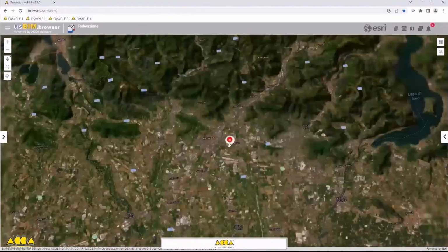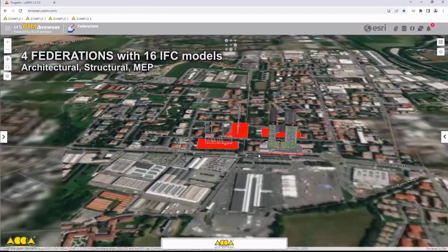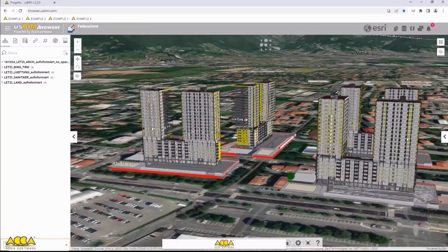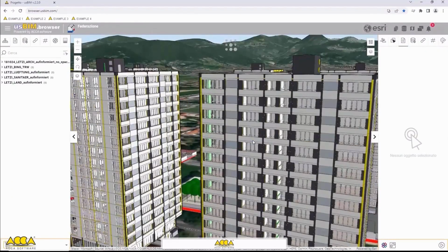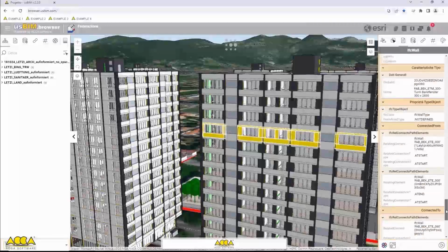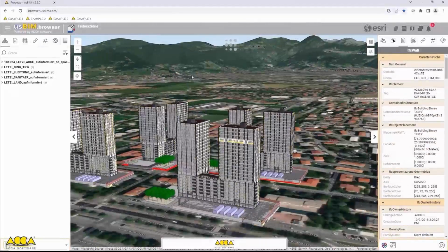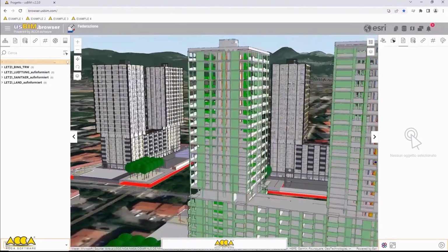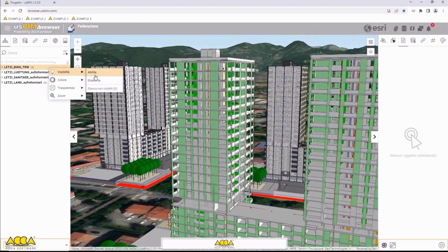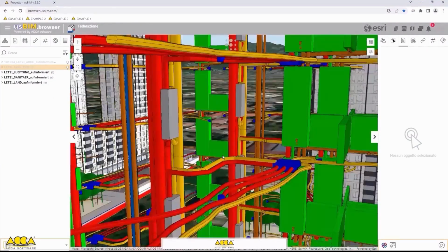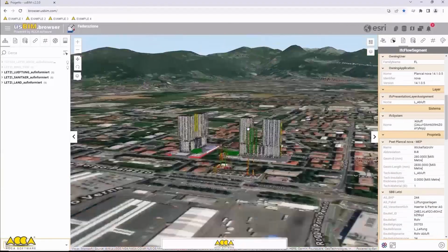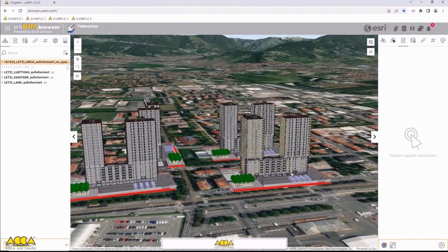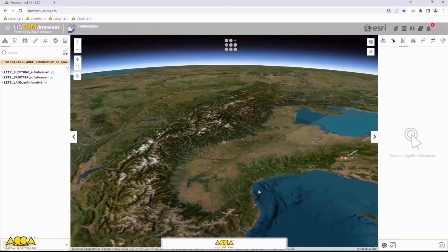This same immersive navigation experience is extended to the territorial context through usBIM GeoTwin. Here, you can observe the same residential complex, now georeferenced within its real-world context. The interaction remains consistent, allowing you to isolate and focus on specific aspects of the model, such as viewing only the structural or MEP components while excluding the architectural layer. You can interrogate individual entities within the model, enabling a journey from the microscopic scale, such as inspecting a single connector within the MEP system, to a macroscopic global scale.